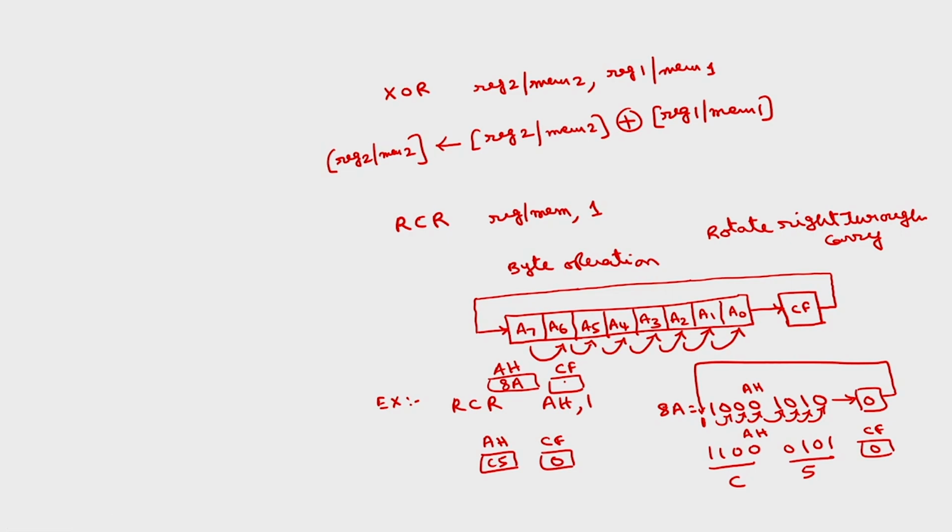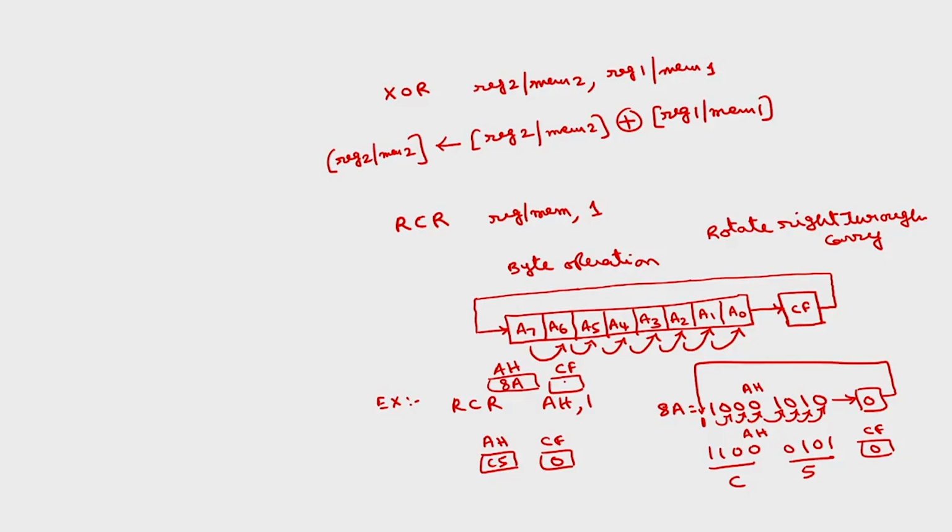So, for the contents of a 16-bit register, the similar operation will take place. The contents of A15 will become the contents of carry, and A0 will in any case transfer to the carry flag. Okay. Similarly, we can have this as a byte from the memory location or word from the memory location. This is if you want to shift by 1 bit position. If I want to shift by 4 bit positions, instead of writing this 4 times, we can directly mention that 4 in a register called CL, which is an implied register.